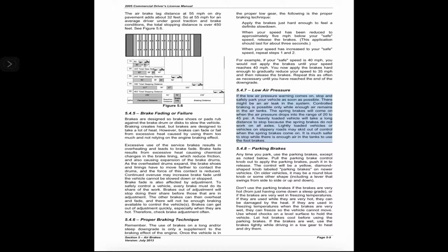A heavily loaded vehicle will take a long distance to stop because the spring brakes do not work on all axles. Lightly loaded vehicles or vehicles on slippery roads may skid out of control when the spring brakes come on. It is much safer to stop while there is enough air in the tanks to use the foot brakes.